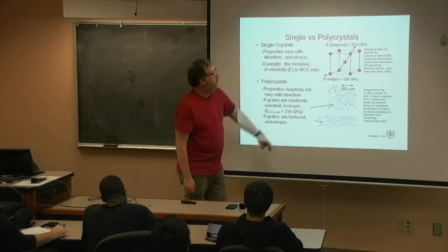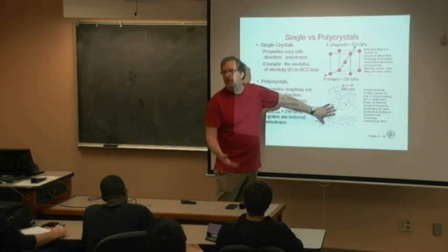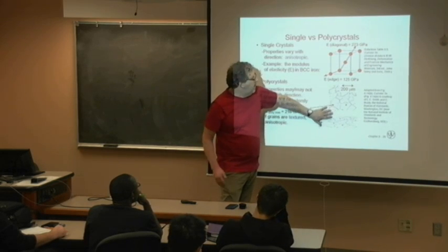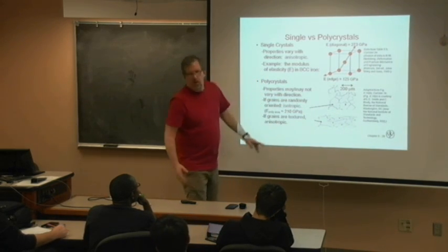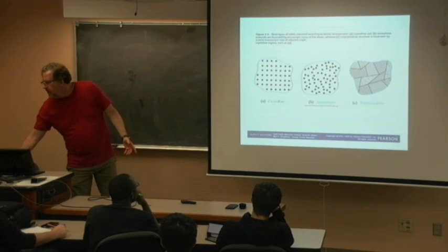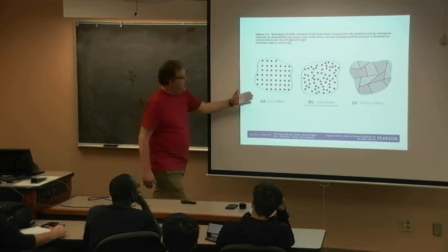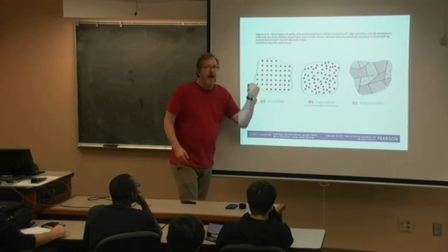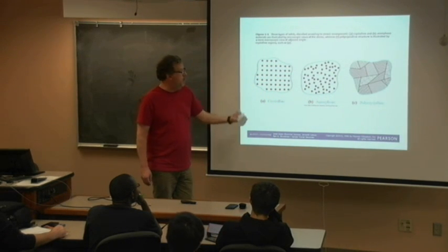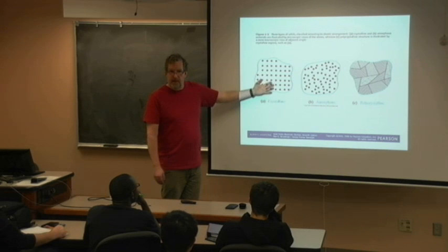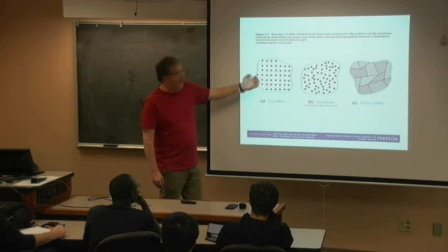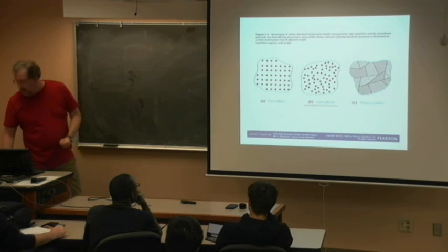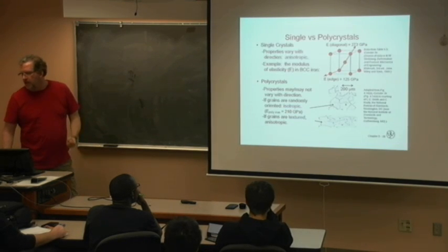It comes up a little bit later, but we can inspect it through microscopes, X-ray diffraction. You'll see later. And so when we make these observations that I have a crystalline, amorphous, or polycrystalline material, recognize I have diagnostic tools at my disposal that could reveal these. That I can actually measure them. Right. So just understand some of those techniques, be able to describe them in simple terms.